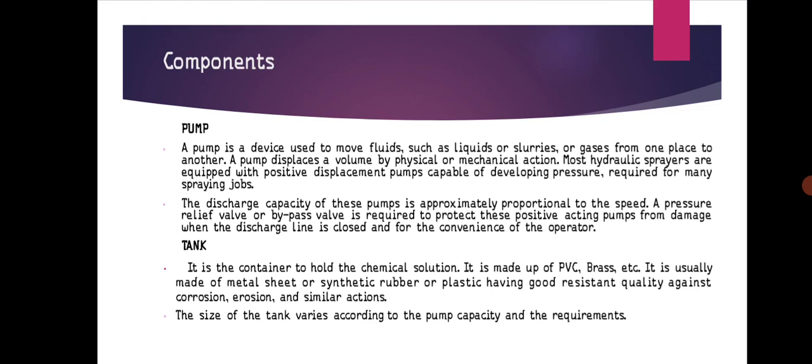Most hydraulic sprayers are equipped with positive displacement pumps capable of developing the pressure required for many spraying jobs. The discharge capacity of these pumps is approximately proportional to the speed. A pressure relief valve or bypass valve is required to protect this positive acting pump from damage when the discharge line is closed and for the convenience of the operator.